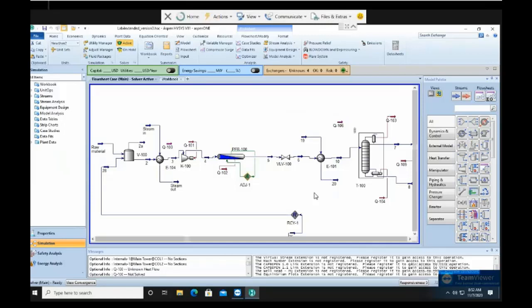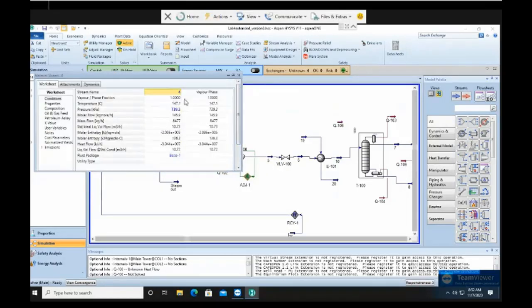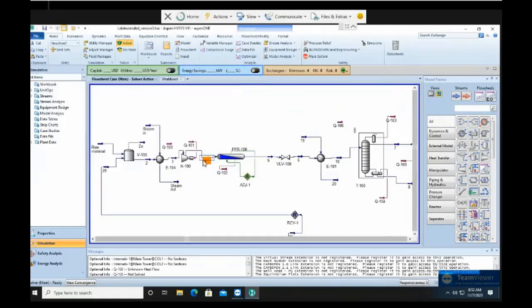But in this case, this is a vapor phase. So usually you have a catalyst. When you have a catalyst, then you must have information on the sizing of the catalyst, the voidage of the catalyst and things like that. So you must have in mind already what type of reactor you want to use before you start your HYSYS. When I read this, I think I already knew, because it says vapor phase cracking.